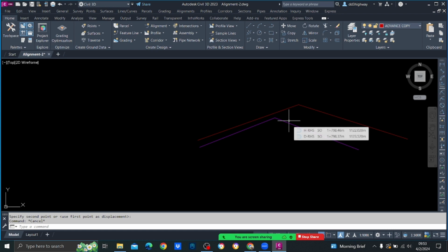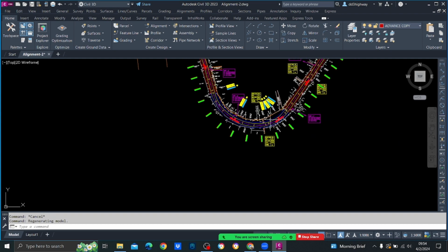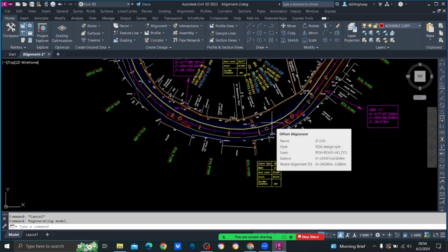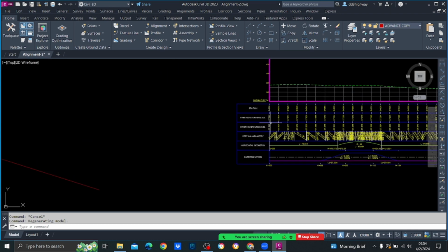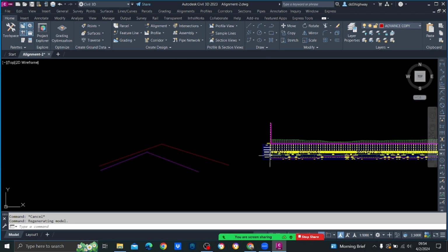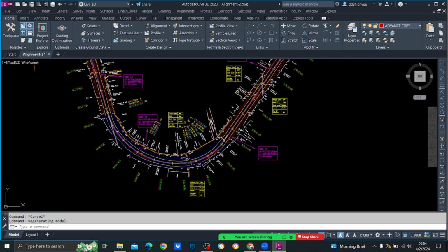But now it is not a big thing. We can do it using Civil 3D. How are we going to do it? We are going to create something called a corridor. In the corridor we run a typical cross section throughout this road, subject to some conditions.